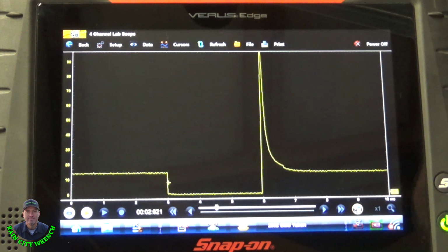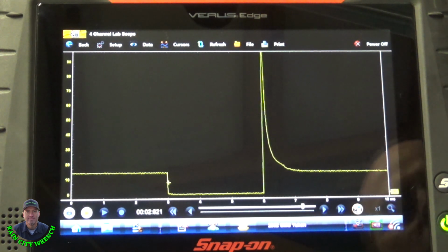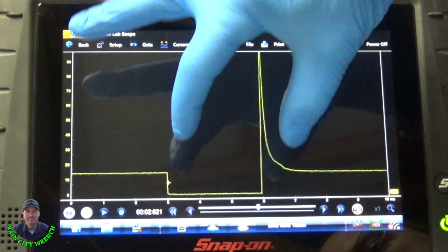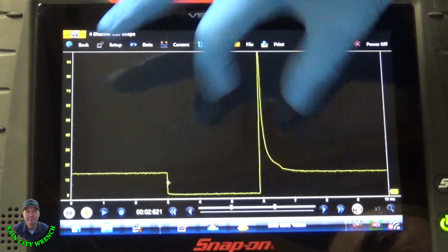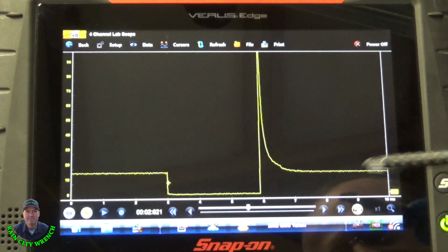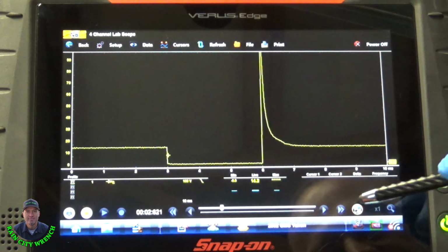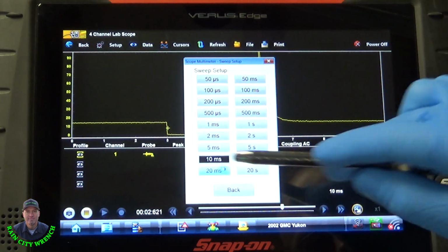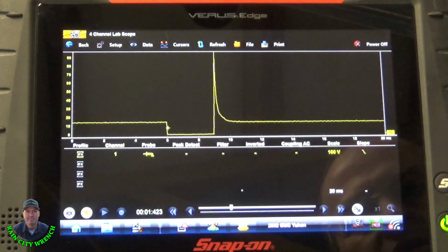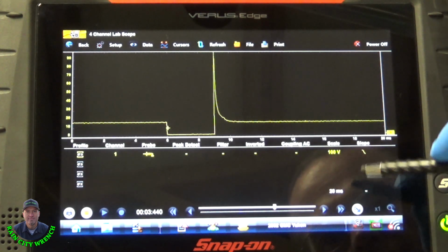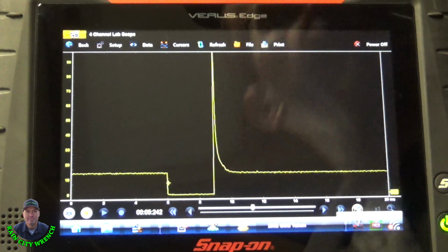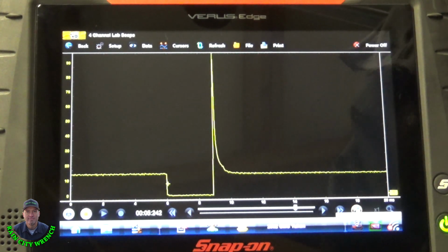Now if I reach over here and increase the throttle, we're going to see the on time increase. It's going to want to spray more fuel. I probably better back out though and go with a longer event. Let's go back to 20 milliseconds. Let me see if I can reach over here and grab the throttle. Yeah, this thing still does have a throttle cable.